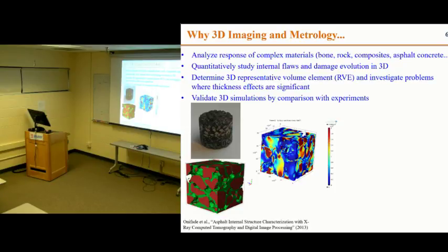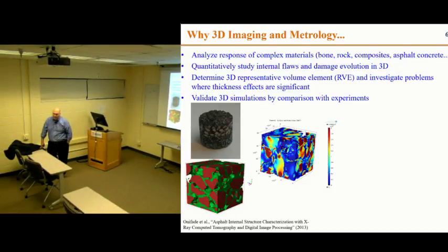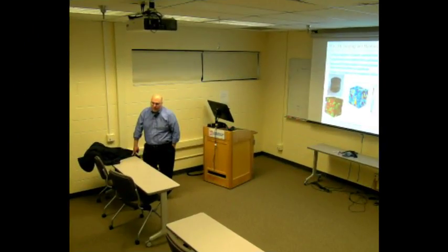How about the explosives? What about the fidelity of the 2D surface strain measurement? Were they satisfied? Not really, no. It has been very difficult to validate complex codes with only 2D measurements. That has been a problem. So what do you do in that respect? What people have done is destructive type measurements. They cut the thing open and then look at the inside. But then it's done, you can't load it anymore after that. So that is also a time-consuming process.